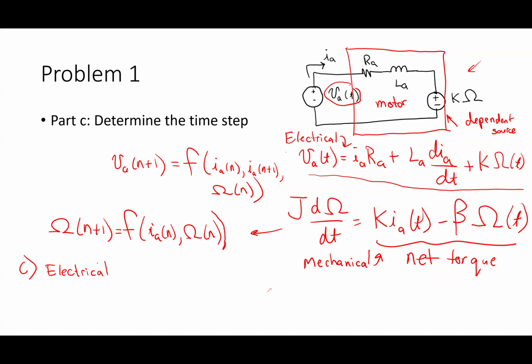So for the electrical circuit, what I do is I look at that one and I say, well, let's set omega equal to 0. Let's assume the speed was 0. And you could do that. I could basically get something called a brake or a dynamometer, and I could hold the shaft of the machine so it didn't spin, right? The machine didn't spin. This circuit works fine. Just means that this voltage source is basically equal to 0 volts. All right. So basically what I'm left with then is VA equals IA RA plus LA dIA by dt.